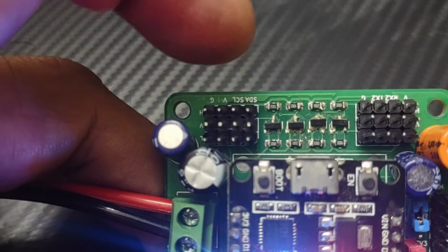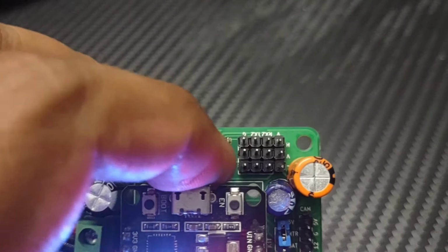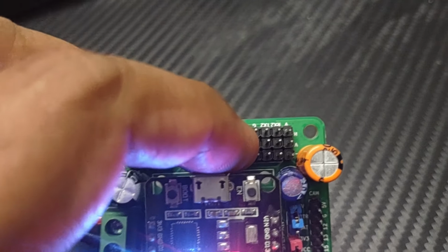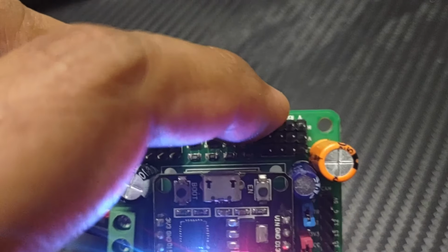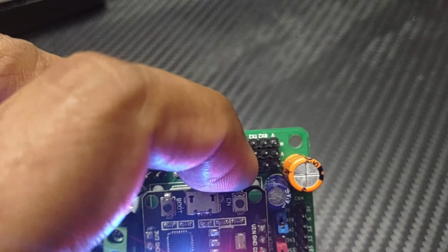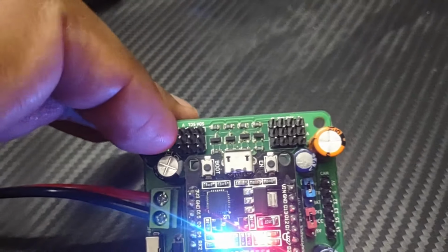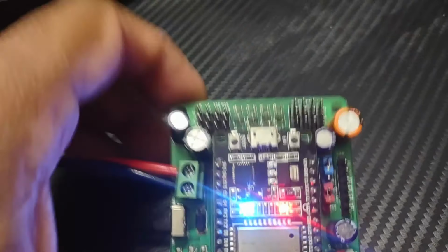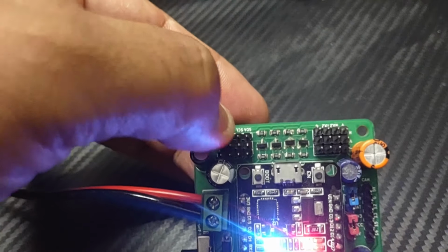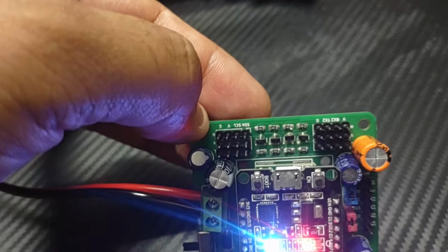And these pins are for serial and I2C. This is the low one, 3.3 volt, the center one is the VCC, so it can be 3.3 or 5 volt, and this is the high one, 5 volt. So if you want a sensor like an accelerometer or something which requires 3.3, you can connect to this first row, or if your VCC is 3.3, you can connect in the second row. And this is the high one.